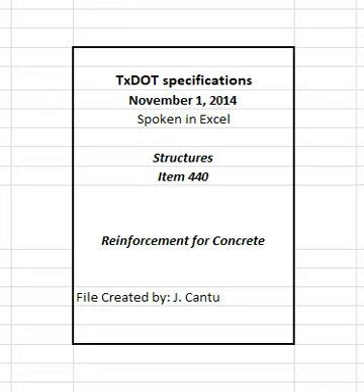3.8 Bending, handling, repairing, and placing GFRP bars. Fabricate, handle, repair, and place GFRP bars in accordance with the TxDOT LRFD Bridge Design Guide specifications for GFRP reinforced concrete bridge decks and traffic railings, Section 5, Construction Specifications. For measurement and payment, the work performed, materials furnished, equipment, labor, tools, and incidentals will not be measured or paid for directly but will be considered subsidiary to pertinent items.